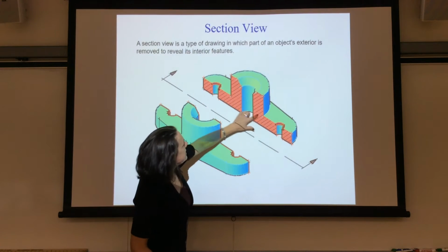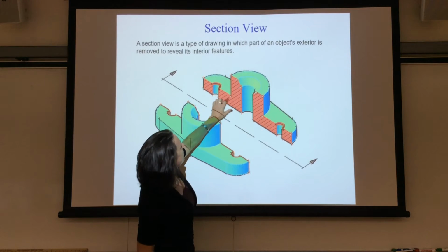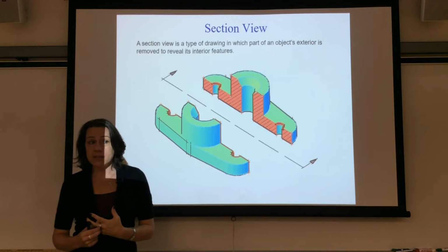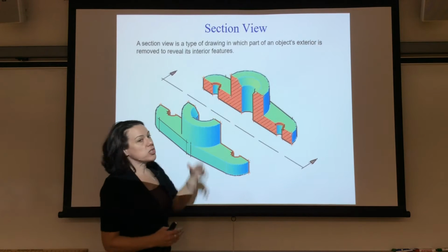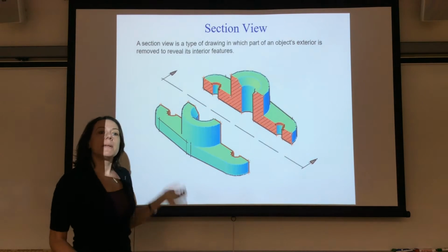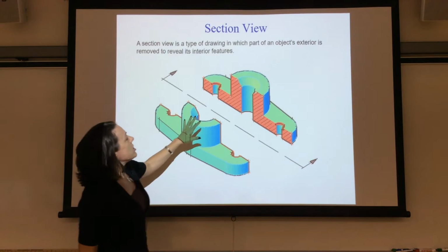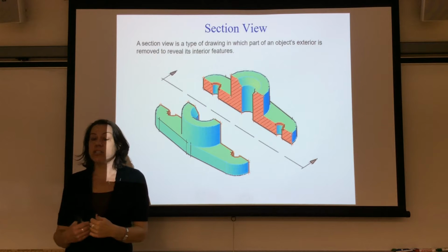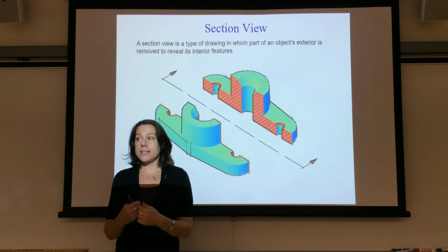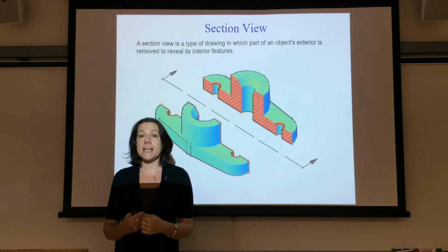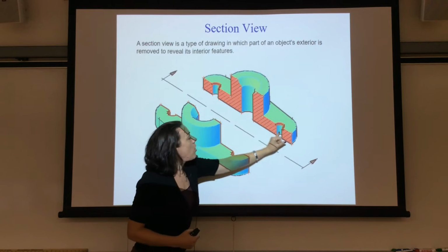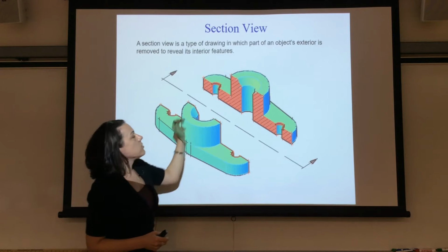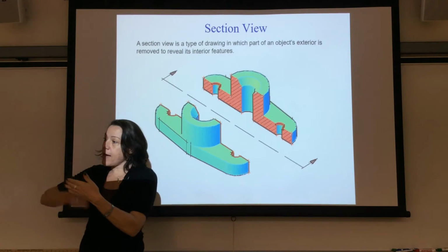And then see these lines here that are in the reddish orange? Those are section lines, or actually hatching lines in CAD. But they're called section lines in engineering drawing. So if somebody says, give me a section view, here's the other thing. Notice what that section area touches. It only touches the solid object, okay? The solid piece that it can cut through. Notice when it goes through the holes, there's no hatching in those areas, okay? Because those holes, it's empty space where that cutting plane goes.